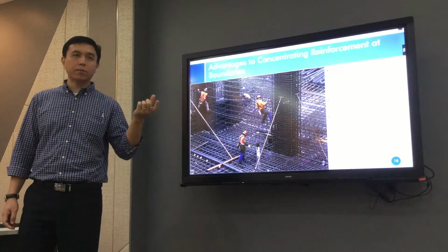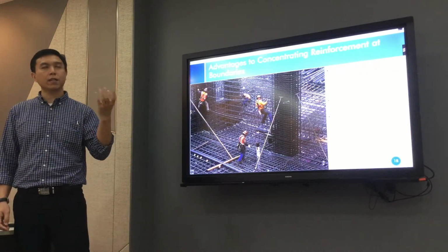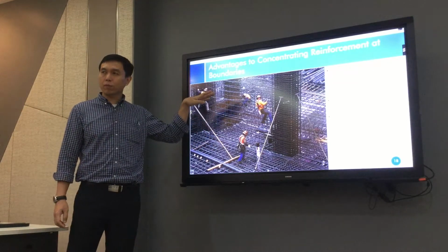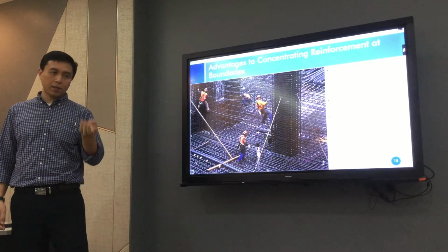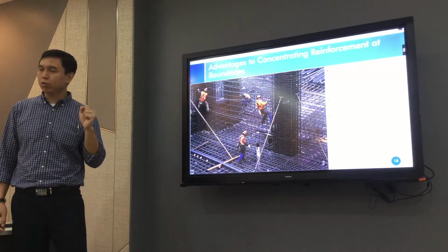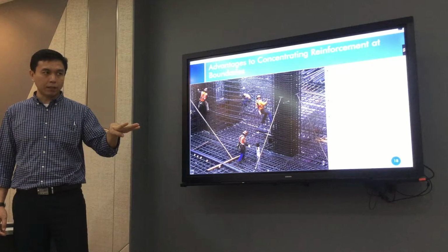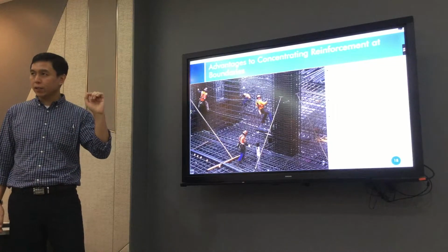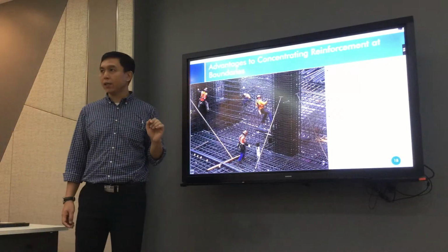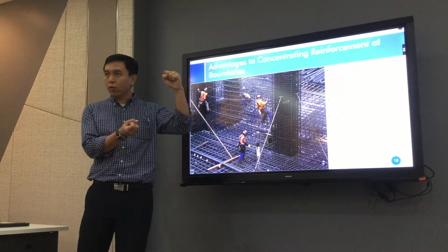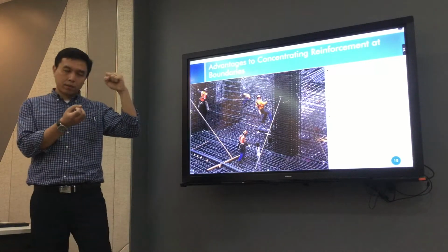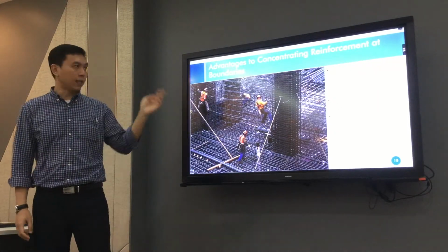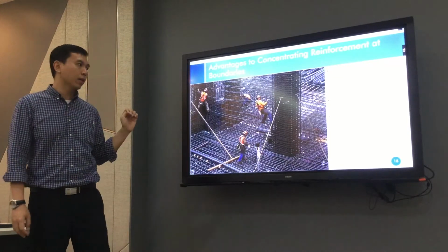For example, in a singly reinforced beam, if you have only bottom reinforcement and no top reinforcement for compression, you will get, let's say, 500 kilonewton meter moment capacity, yielding capacity. But if you provide top bars for the compression, the moment capacity is not significantly increased. The beam becomes doubly reinforced. Moment capacity is almost the same, a little bit of increase, but the gain is in ductility. The moment curvature curve will become more ductile.